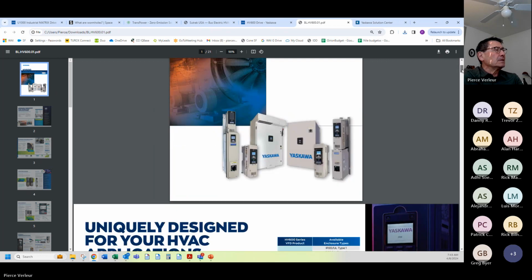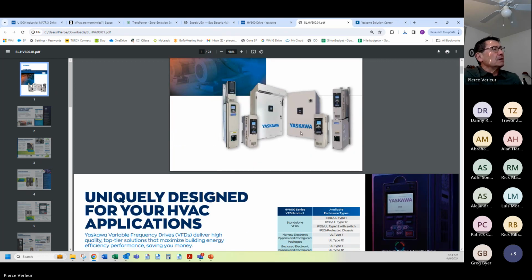Now, basic drives with bypass. So this is an over-under configuration. Here's another basic drive with bypass. This happens to be the electronic version of it, so the keypad is actually on the front end of the bypass container. Note, these are tall, skinny, because in buildings you've got a lot of height but you don't have a lot of width. So to make more use of the location, you want a tall, skinny drive.